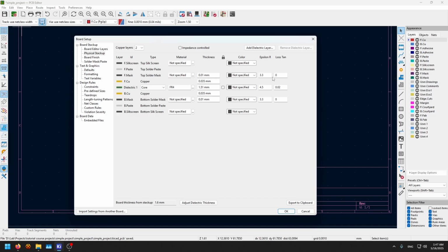Basically it's FR4. For example, the copper layers are 0.035 millimeter, etc. The color, whatever. But these, I don't really recommend you play with these unless you really want a certain stackup and the widths and stuff like that are not standard. Basically, you can put them in here. Very simple. But for almost all people, you're gonna leave these the way they are.